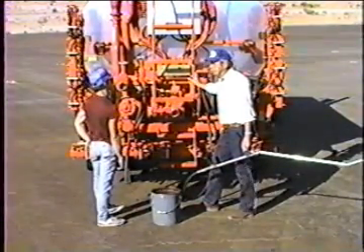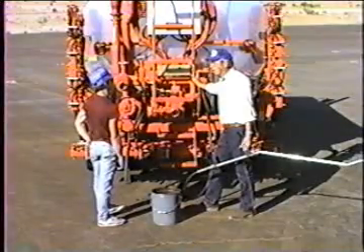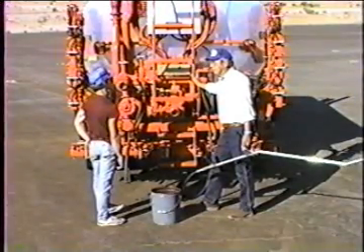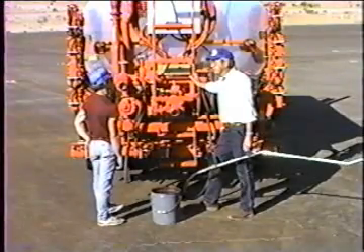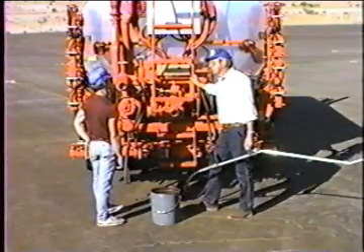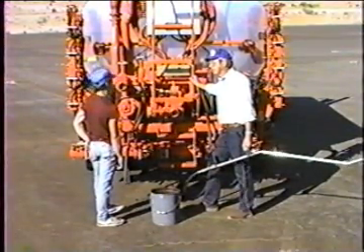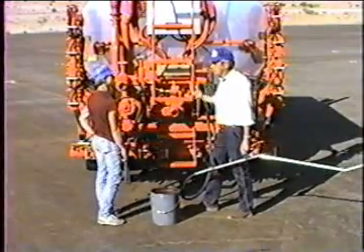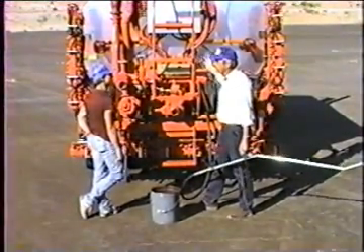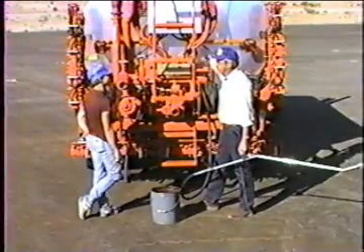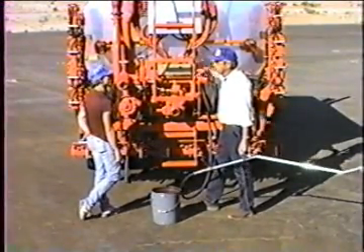Not that it hurts it any, it doesn't do a thing as far as harming the asphalt, but what it does do is ruin the test that they use. They have a test where they test the flash point of the asphalt to see that they're getting pure paving grade asphalt. If you put a gallon of diesel in this tank full of paving grade asphalt, it totally ruins that flash point test.